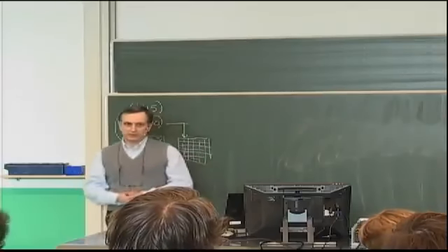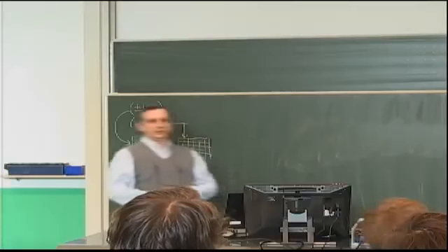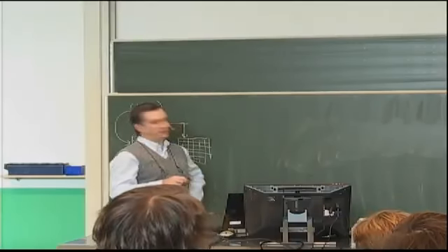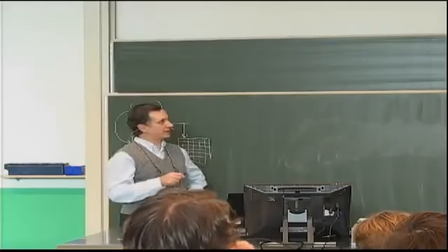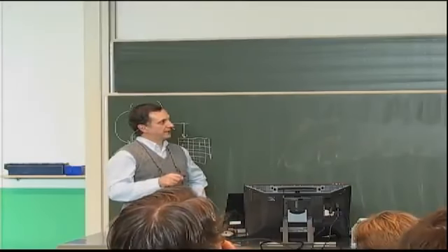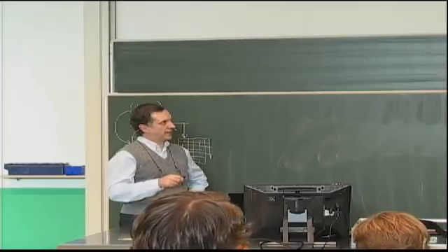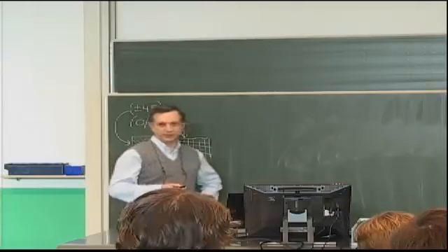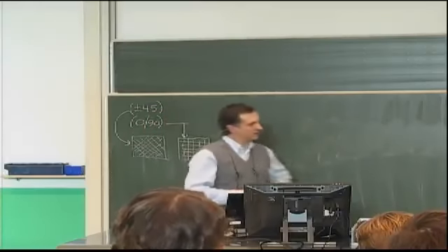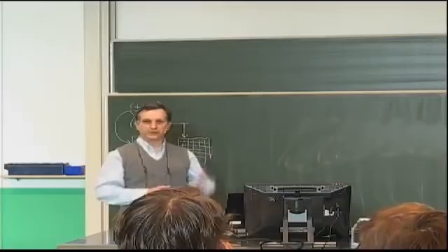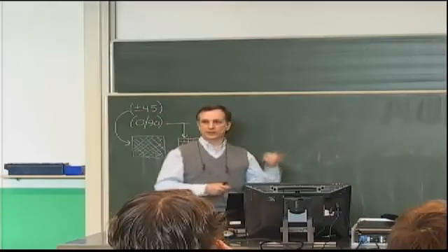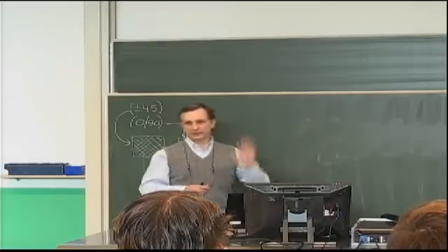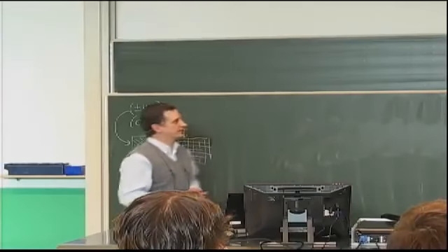We said it's a simply supported plate, so we will assume now for a solution to this governing equation, a solution that satisfies simply supported boundary conditions. W is the out-of-plane deflection, and at x equals 0 or a, and y equals 0 or b, because of the sines being present, W is 0. So that satisfies the boundary condition. And this one, compared to the previous one, which was a single Fourier cosine series in y, now it's a double Fourier series because I have both the x terms and the y terms in terms of sines in this